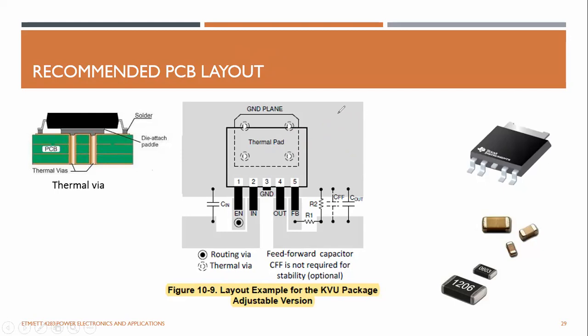So in double layer PCBs, you can have this top layer filled with a copper pour, and also make an additional copper layer on the other side, and you can put some thermal vias, so that will transfer the heat of this device to the top plane, and from the top plane it will dissipate to the outside.